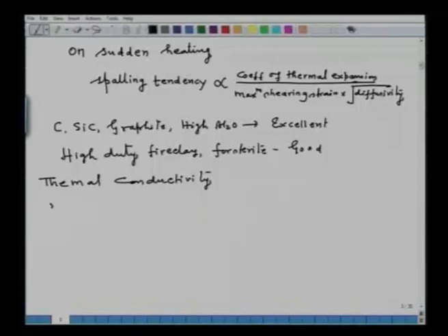They can be used only for heat loss purposes, one of the main objectives of bricks having low thermal conductivity. Of course, chemical composition is important in the sense, as you recall now, the bricks or the refractory material comprise SiO2, Al2O3, MgO and so on, and the same oxides are there also in the slag.